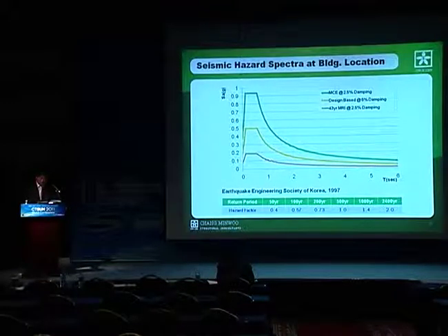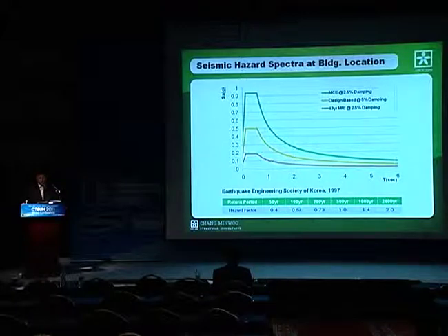And the seismic hazard spectrum was evaluated using the hazard factor. Korea does not have enough earthquake data to establish the relationship between seismic hazard and natural period. So the hazard factor, which was provided by the Earthquake Engineering Society of Korea, was used in this research. It's shown in the table at the bottom.